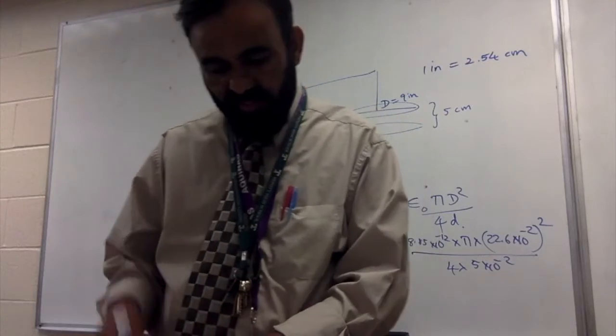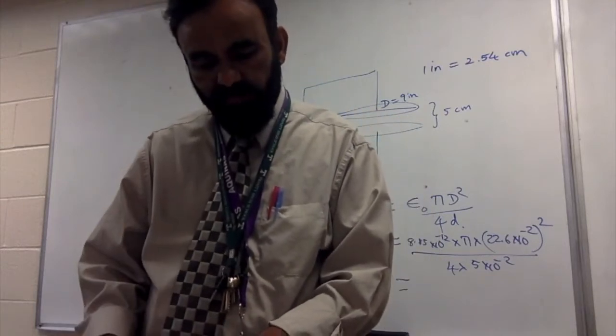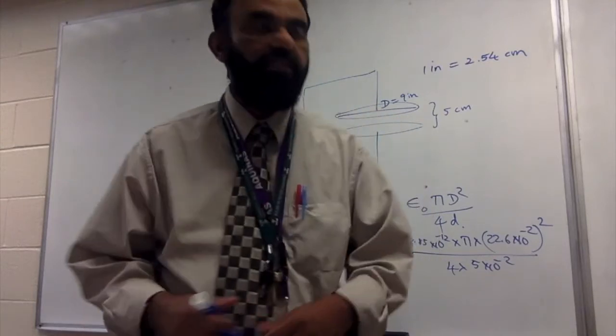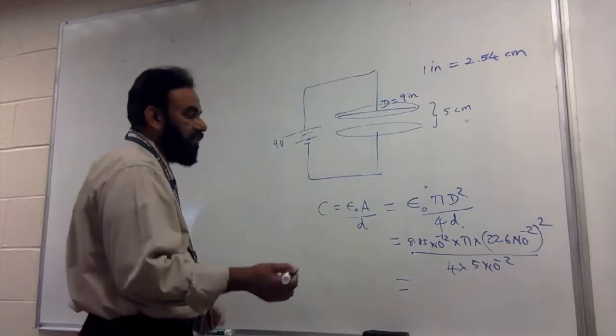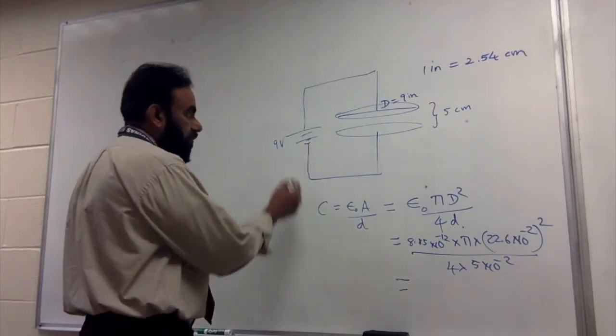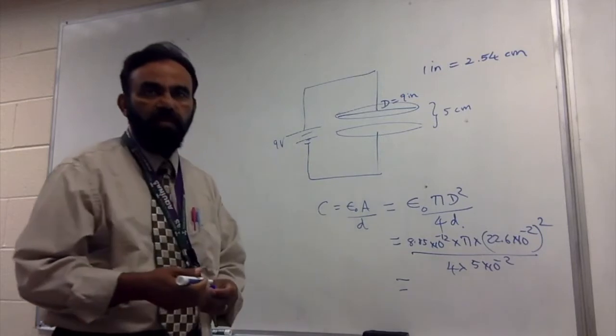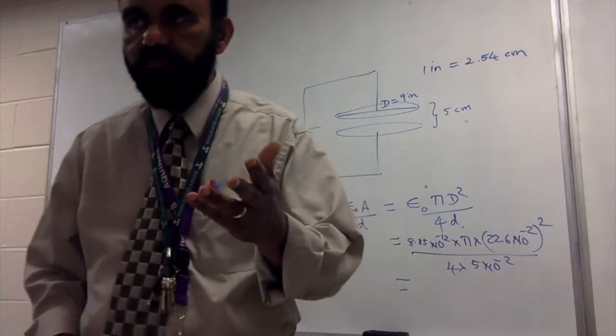Next question on the same. They're asking what's the charge on each plate. So you know how to find the charge, right? You know the voltage, you know the capacitance, multiply them, you get the charge, right?